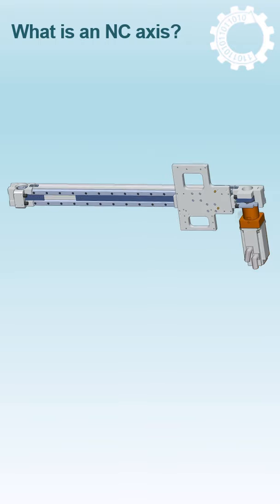The rotation movement is converted to a linear movement using a ball screw and nut, or using a lead screw and nut, or using a rack and pinion system, or, like in our case, using a timing belt and pulley. This way, the linear movement is transmitted from the motor all the way to the moving plate. To prevent damage, the movement is limited on both sides using bumpers.